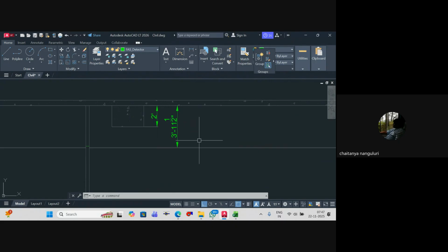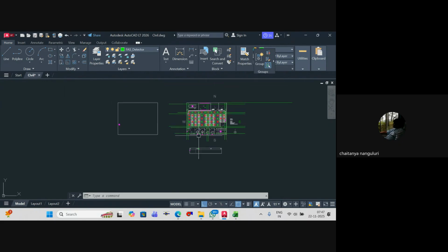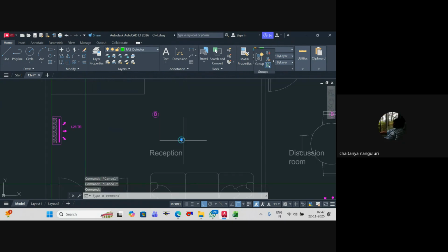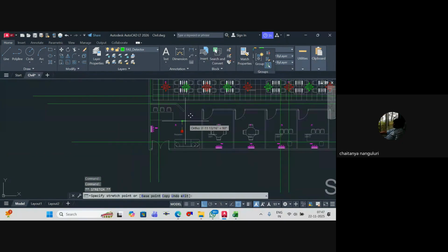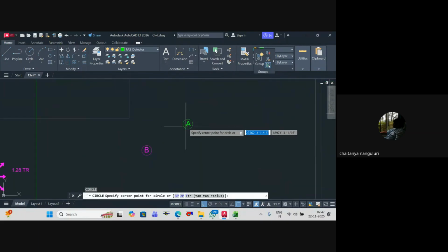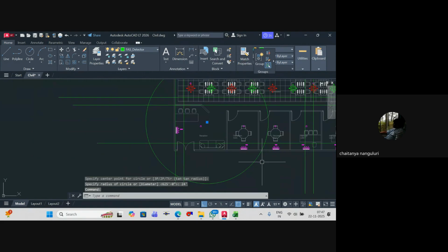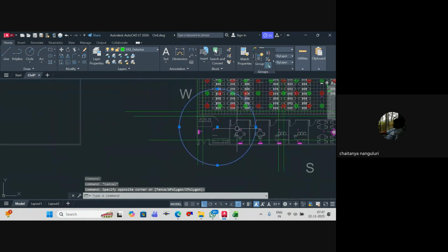That's what I've told you. 99.9% between the false ceiling and the slab, the beam height is anyway more than 10%, is what I've said. 99.9% of jobs. Understood? Yes. So your detectors will be at this location. So in this zone entirely, I can draw a circle of 7.5 meters, means 24 feet. I'll draw a distance of 24. I'll mark it with a different color. So I'll do this particular one.